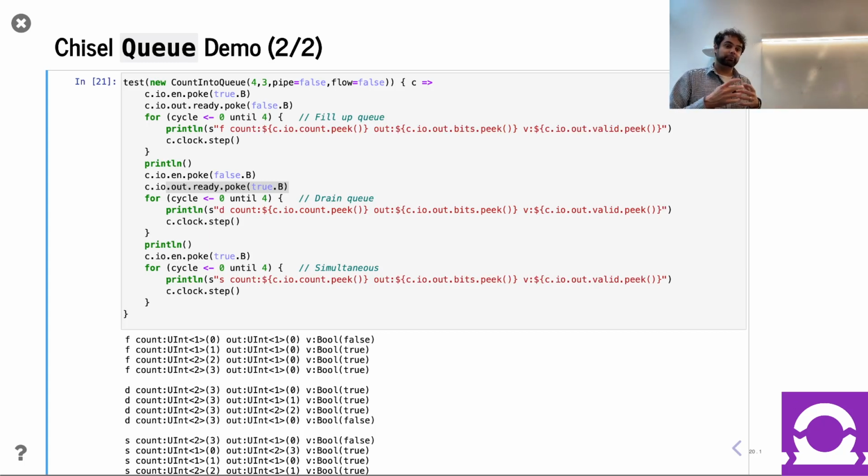The simulators are designed to randomly pick values for wires or registers. So I think some people on the prior homework noticed, oh yeah, if I did or did not use reginit, things did not work. Oh, sorry, that was lab 2, not the homework. Yeah, using reginit is usually a pretty good idea because that would make sure the registers have a value you know. If you don't set the value intentionally, it could be an arbitrary value.